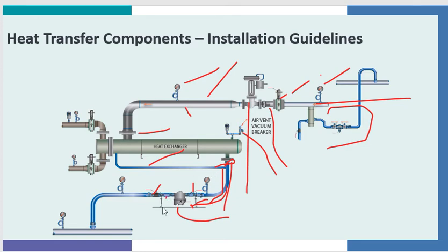The other question is, do we need a check valve? It depends on the system. Recently we put in 3,000 steam traps, and not one of them had a check valve after it. Only put a check valve in if you have backflow that can occur.